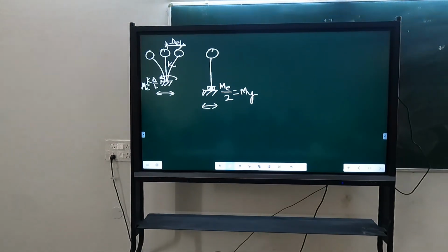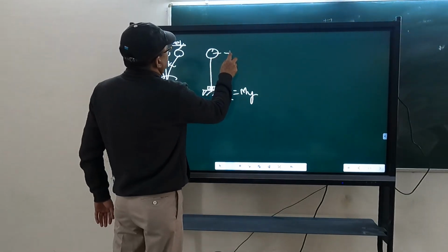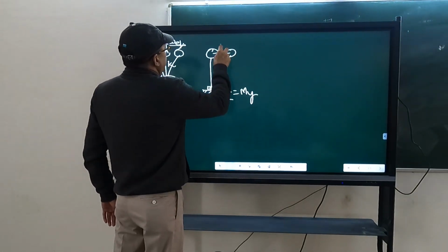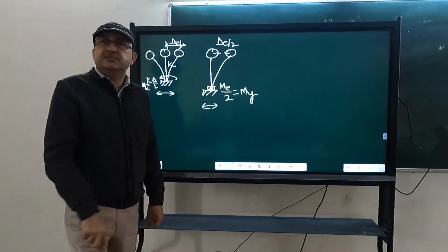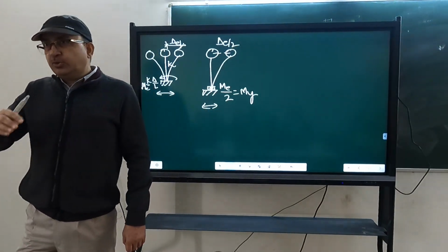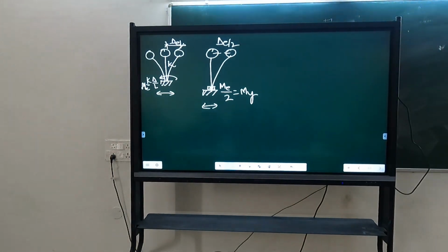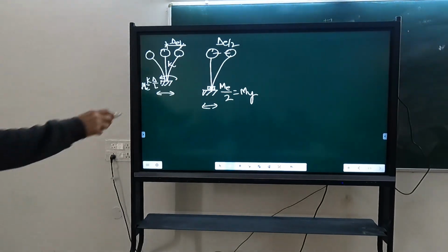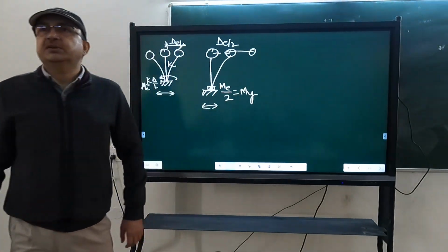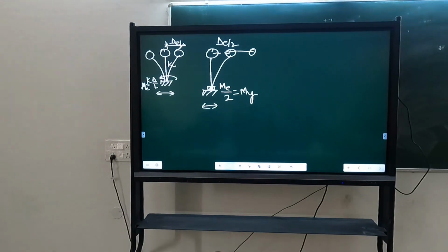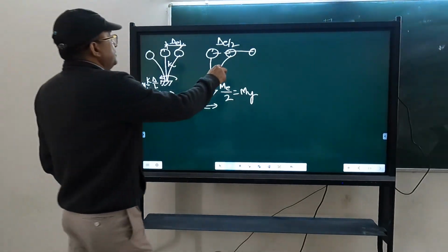So this displacement continues. When it is delta E by 2, you will see it will reach My. So at delta E by 2 itself, it will reach My. What will happen then? Will it collapse? It will continue with plastic deformation here. Plastic rotation will occur. It will continue. How much will be this displacement?